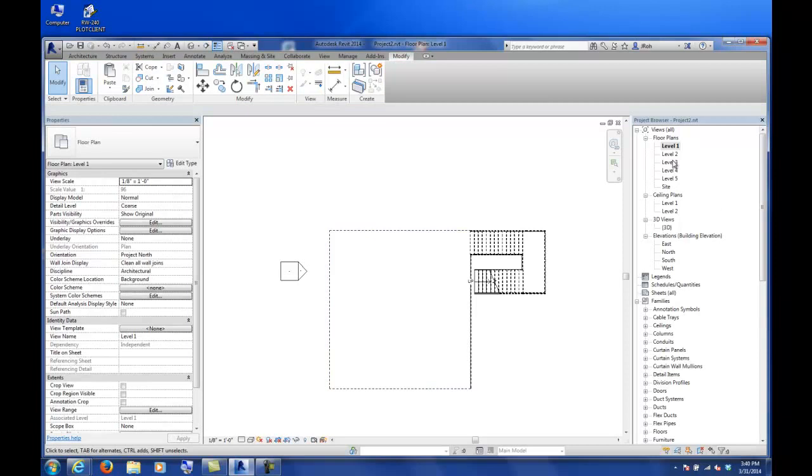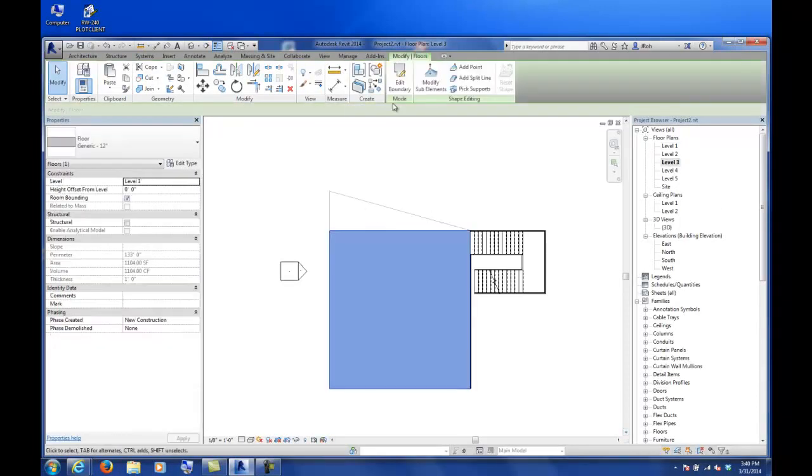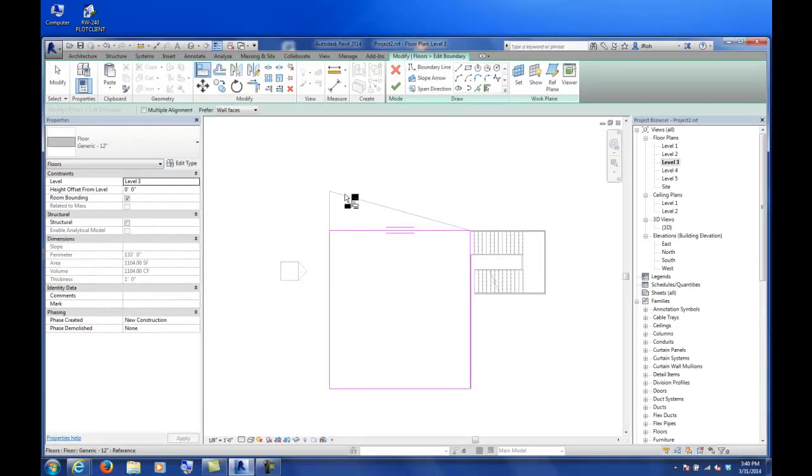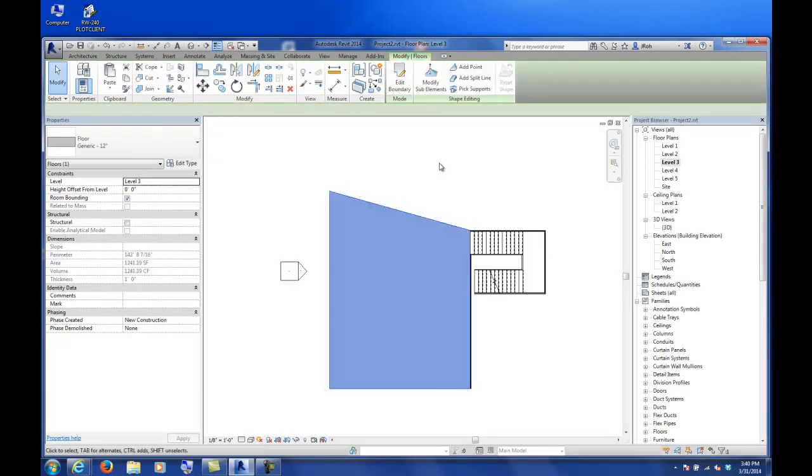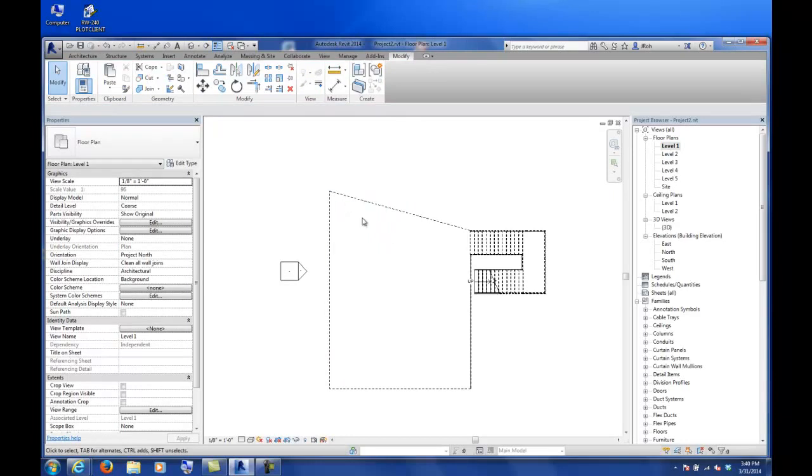Wonder why that happened. How did you figure out what lines you were actually turning into dotted lines? So in level 1, there we go, that updated. All I did was, if you highlight your floor plans, you can turn on the underlay for any floor plan that's already created. And all I did is I went to another floor plan, like level 3 or level 2, as the underlay. Then I used my line work tool and I hovered over each of the lines that were associated with that floor slab, and it basically attached a dashed line to it.